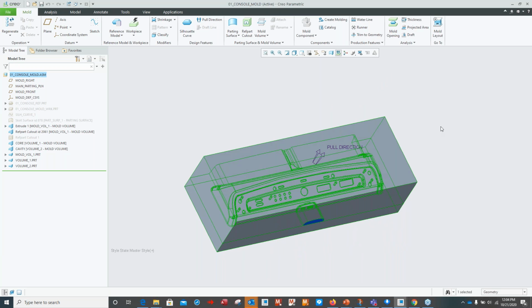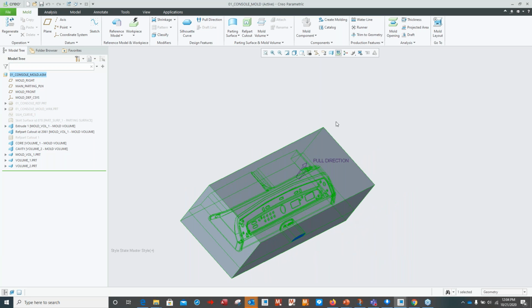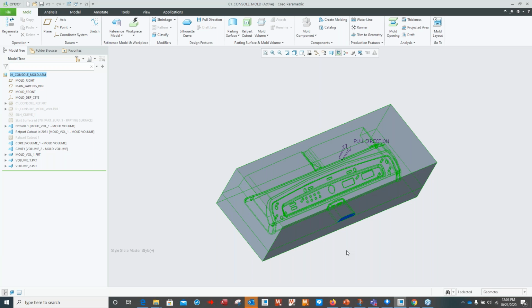Honestly, it's something that is probably more done in the mold layout, not necessarily in this area, because you still have to go through other areas, and it just would seem streamlined, because if you're even doing your ejector pins, you can put those ejector pin locations in here, but when you go and build the whole entire mold, you have to do that through the rest of the geometry, and all that other geometry is not in here. So again, this is a great and powerful tool for developing parting lines and shutoffs relatively quickly.